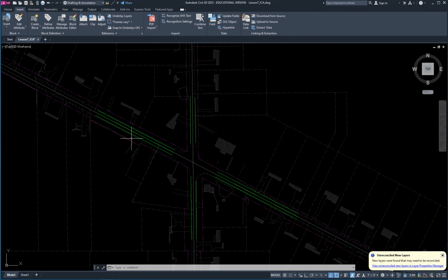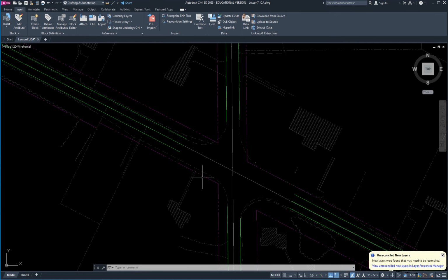Right, so I've got that in, and now according to instructions, I'm going to put in my radiuses on these corners and on these obtuse angles, these larger angles. The radius is supposed to be 120 feet. On the acute angles, over here, the radius is 60 feet.